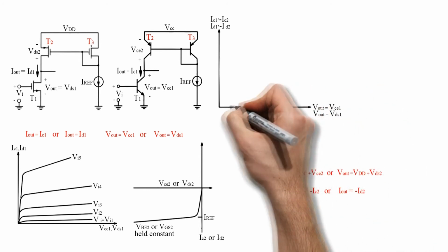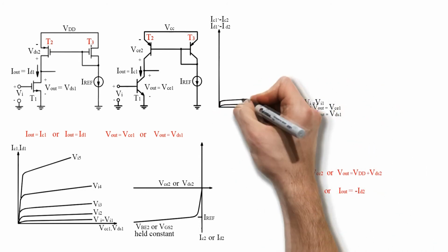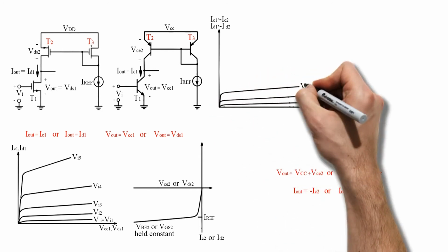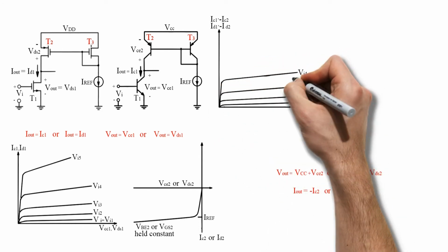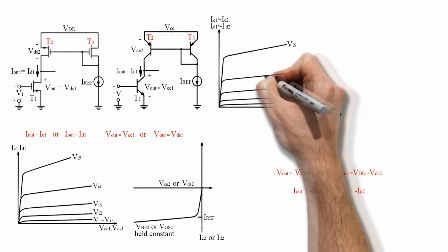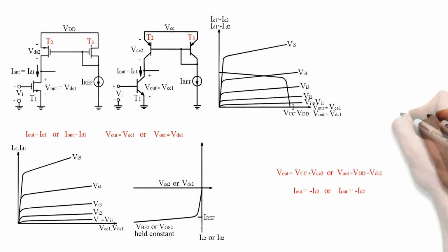We now consider the DC transfer characteristic of the circuits. Initially, assume Vi equals 0. Then the input transistor is turned off and the load is saturated in the bipolar case and linear in the MOS case, corresponding to point 1 in Figure 4.17c. As Vi is increased, the input transistor eventually begins to conduct current, but the load remains saturated or linear until